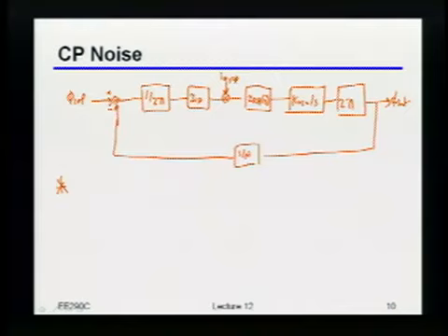So what would be the transfer function we'd get from that charge pump noise current to phase noise at the output, or really to jitter at the output? Scaled version. There we go. It's the same as the reference. It's just scaled, right? But what is it scaled by? ICP over 2 pi.